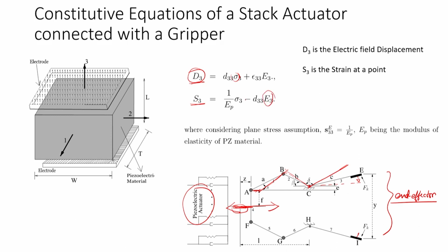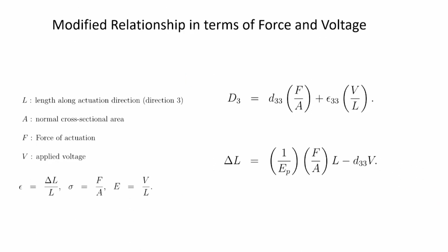The negative sign I have given here, because that corresponds to tension positive. So, you can create a compression or tension in the system. It is just a matter of sign convention. And each one of these piezoelectric systems, if you look at it, the piezoelectric material has electrode coating on top and bottom, and that electrode coating is applying the voltage, so that the deformation is happening in the system.